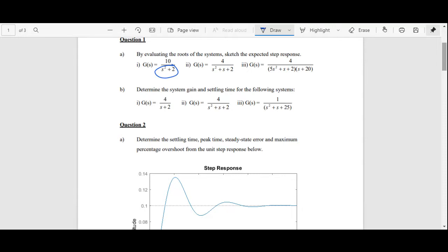It will be oscillatory forever. It will never die down. So we have to distinguish between being oscillatory and being constantly oscillatory. Because, of course, you can have an underdamped system being oscillatory, but over time, as time progresses, it settles down.